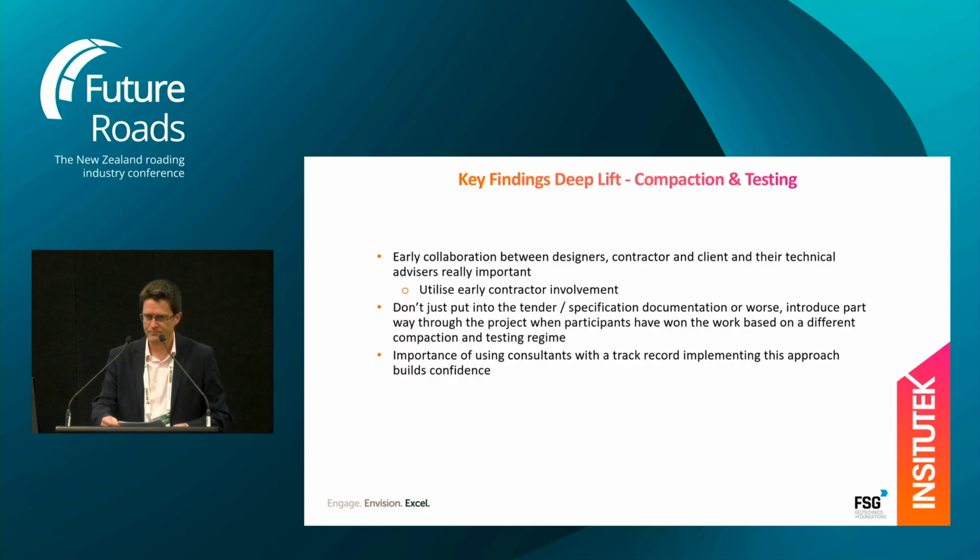And you didn't talk about vibration there. Great point, thank you. For stiffness assessment, you must have vibration on the rollers, okay? And absolutely, vibration was used for that compaction. So thank you very much.